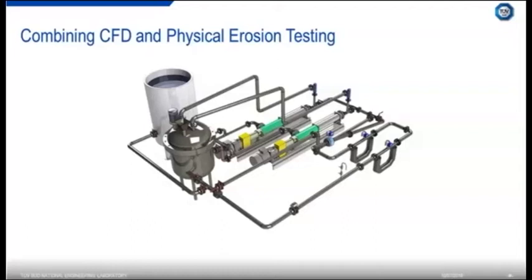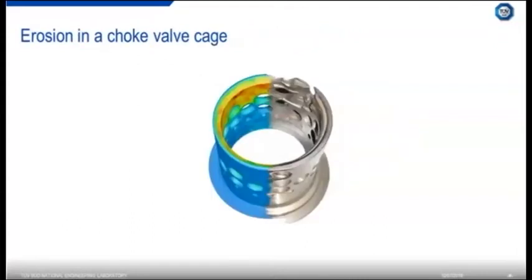The picture here is a 3D model of NEL's erosive flow loop. It's a sandy water flow loop, and we use this to test valves and other components under sandy conditions. We use it to do things like simulate field life of components. So we do accelerated testing, and we can use tools such as dimensional measurement and weight loss measurements to characterize material loss for given field conditions. So you can use the data from a physical test to update and tweak your CFD model.